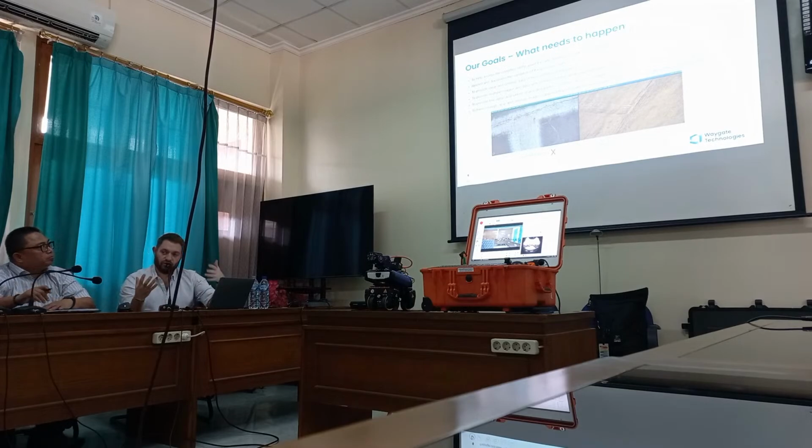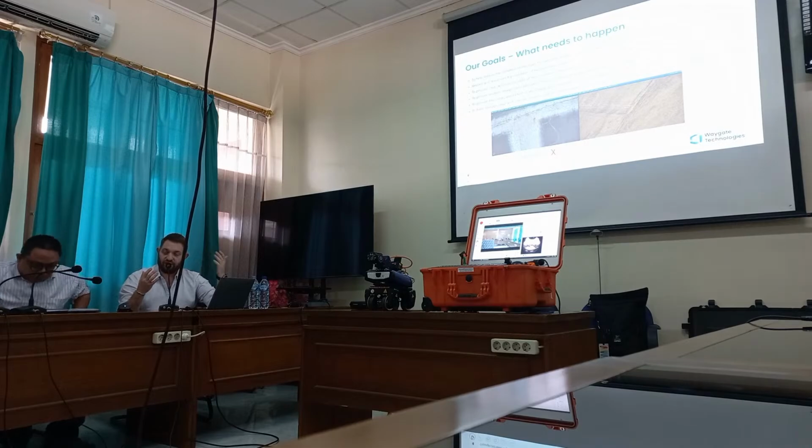So when we perform inspection, we ourselves have a number of goals that we have to achieve. Our primary objective is to help collect and gather the data for our client, obviously. We need to record it, document the condition, both good and bad, as accurately as we can. Because if we've seen an area that's a good representative sample of, say, the shell in a pressure vessel is not corroding, it's okay. We want images and data of that.